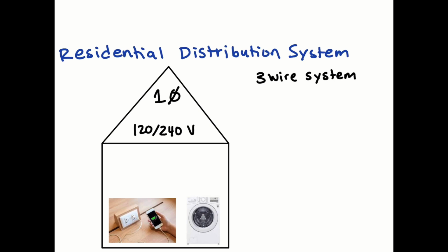The primary distribution system is part of the AC distribution system, which operates at voltages slightly higher than general utilization. The voltage used for primary distribution depends upon the amount of power to be transferred and distance of substations required to be fed. The commonly used primary distribution voltages are 11 kilovolts, 6.6 kilovolts, and 3.3 kilovolts. The primary distribution is done by 3-phase, 3-wire systems because of economic considerations.